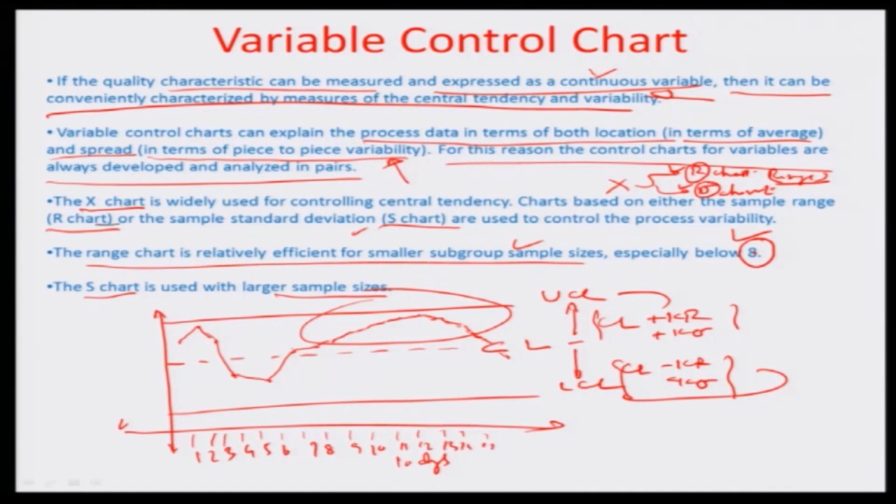So you can see that beyond the 7th day there has been a significant deviation in the way that the control variable is being plotted here, and so you can ascertain that something happened during the 7th day and beyond which caused this process to become more like an outlier from the mean tendency of the process. So very quickly you can see